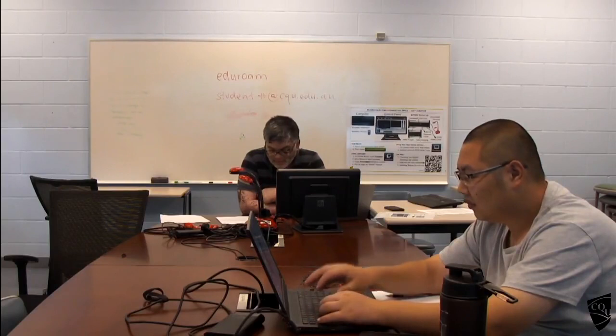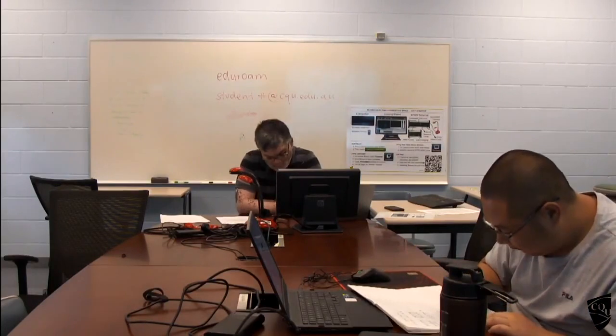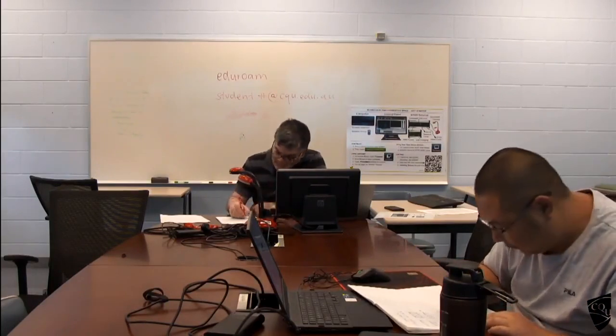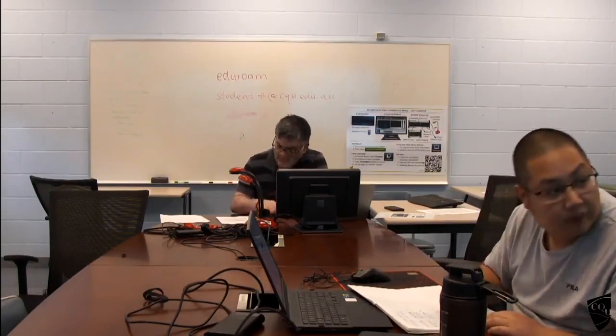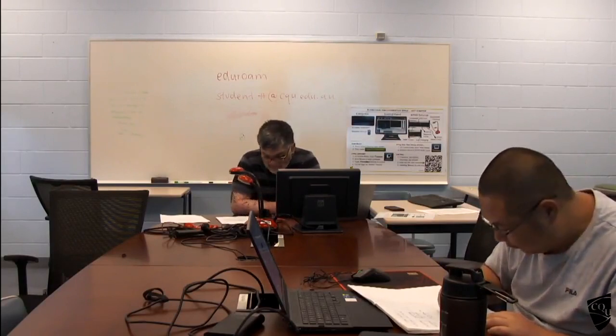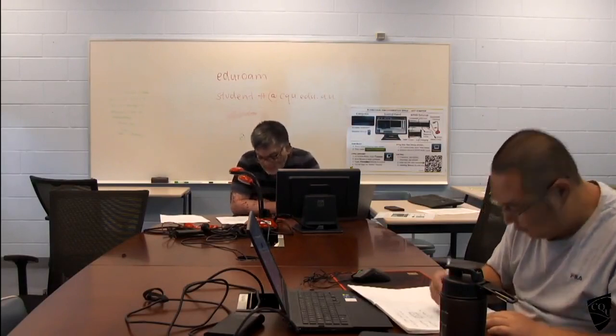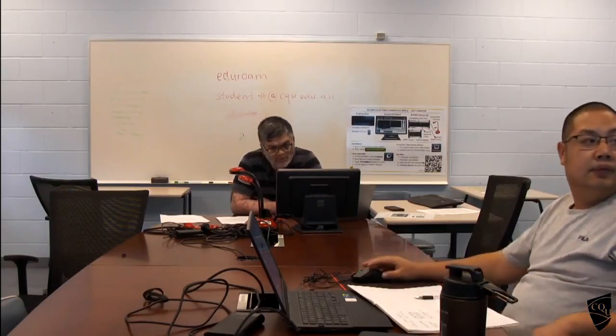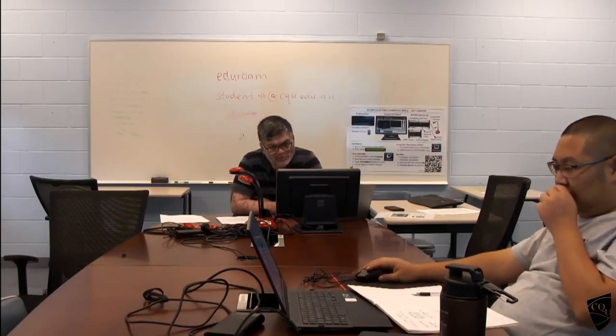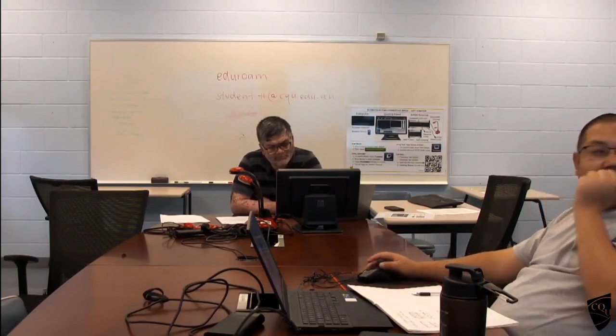Then what is the self weight? To find the self weight, this is D times rho concrete. Depth of the slab, I put Ds, depth of the slab times rho concrete. Rho concrete is the density of concrete. Use 25, not 24.